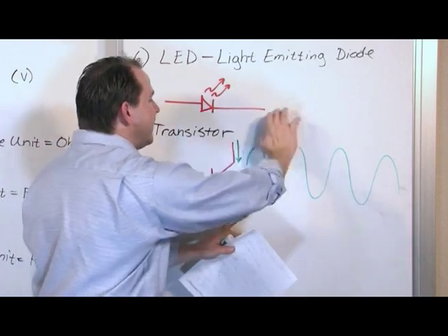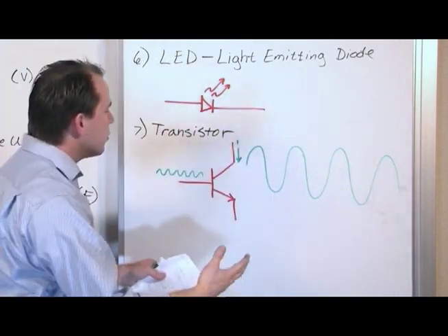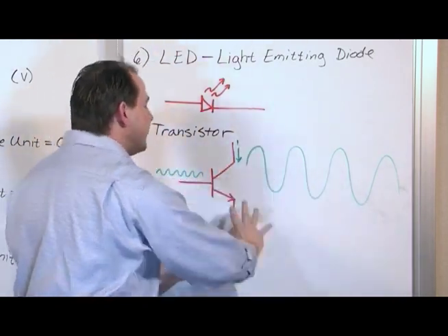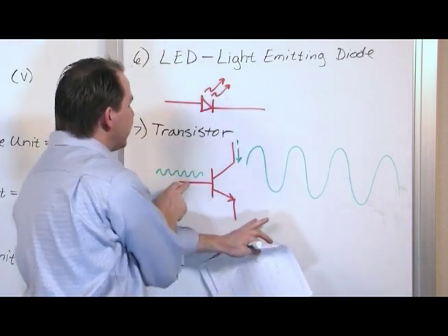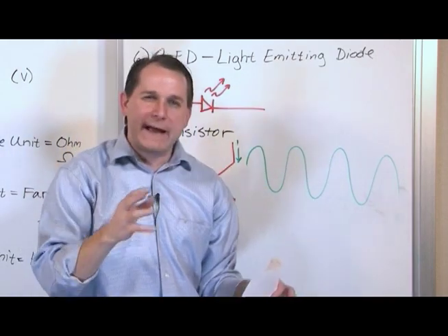Like maybe I have an entire thing going on over here, a fan, a motor, maybe I have 50 more transistors here, maybe I've got something crazy over here, but I've isolated it through this transistor. This guy's not even functioning unless I turn it on by sending a signal in here, right? So that's how it behaves as a switch.